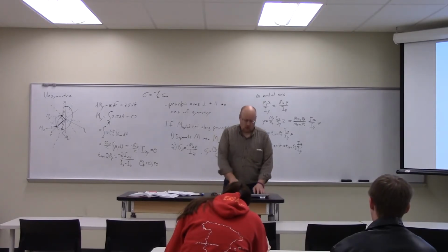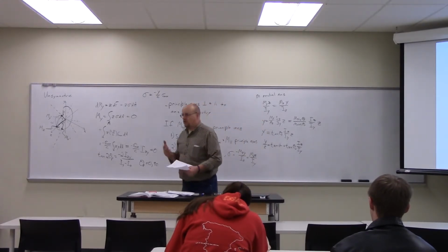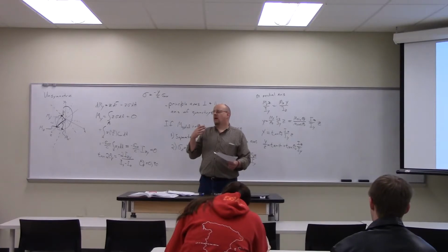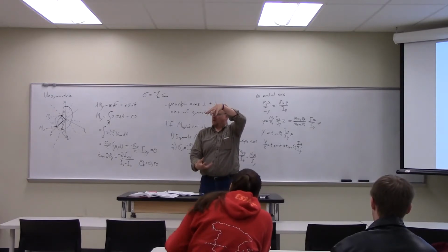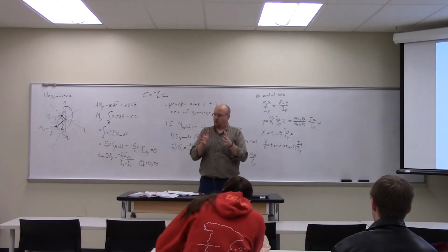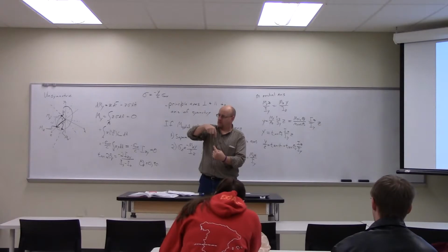Generally, even when you combine them, there's an interaction between shear stress and normal stress, which creates a Poisson contraction or expansion. Remember Poisson's ratio? If I squeeze a piece of rubber like this, it gets bigger like this. So there's a strain in the lateral dimension when I squish in the longitudinal direction, or if I pull in the longitudinal direction, there's a strain the opposite way.